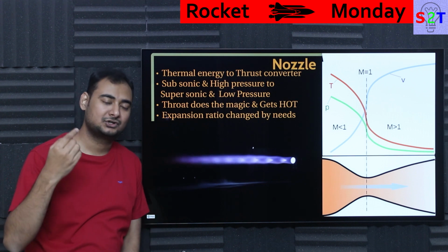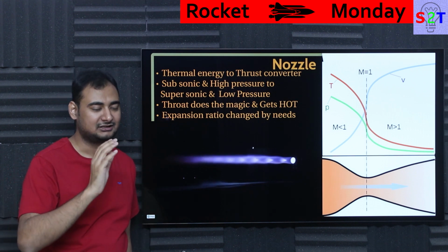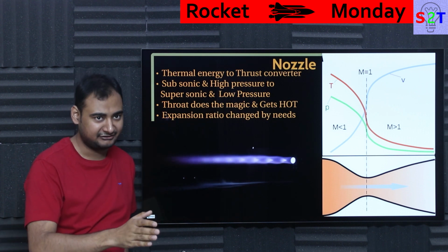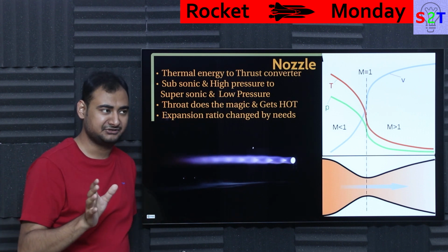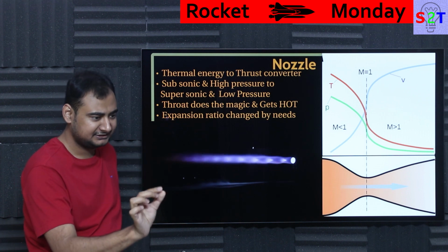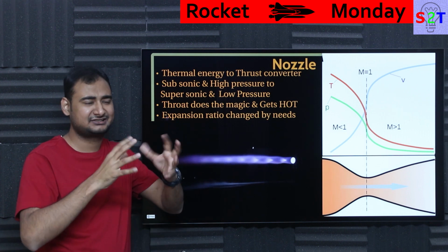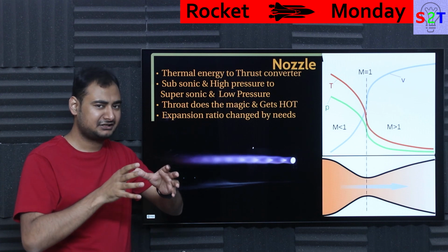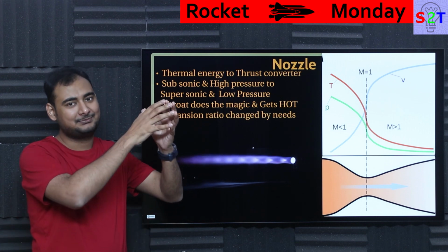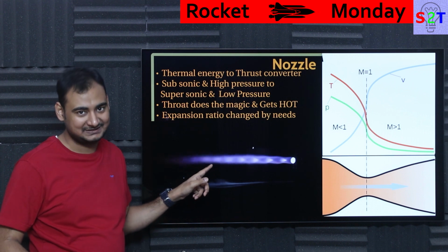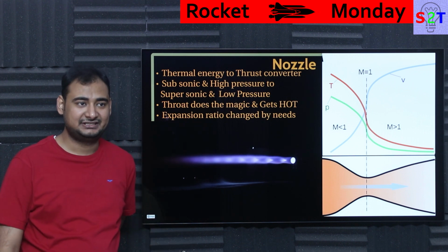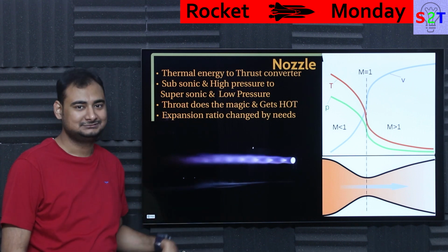And that's why if you ever watched any Saturn V launch, where F1 engines are running, and they have very good tracking images, you should check that on YouTube. You will find that as they are going, you're seeing amazing, good looking shock diamonds. Again, it's very dirty, but if you pay attention, you will notice shock diamonds. The moment it starts to go to the upper atmosphere, these shock diamonds disappear. And once you go to 60,000 or 70,000 feet, it's like, yeah, no.